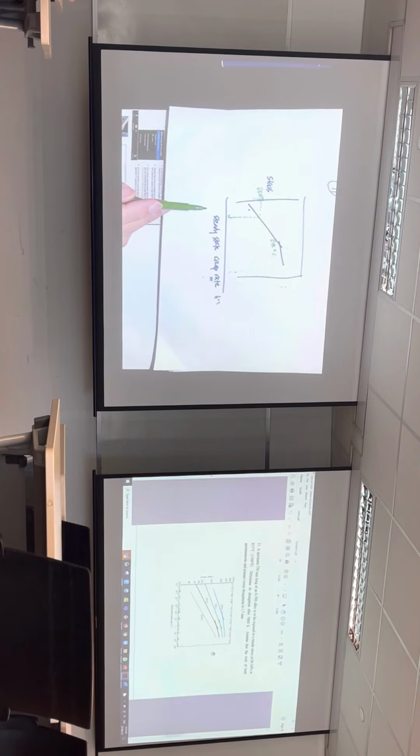The creep rate is how fast it creeps per hour. So, for example, I give you an arbitrary value. If the creep rate is 0.1 per hour, you always extend with time, because creep is a function of time. If I tell you the creep rate is 0.1 per hour, 10 hours, what is the creep? 1. So the creep rate times the time, in very simplistic terms.